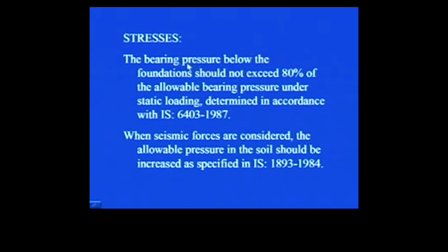Then the bearing pressure below the foundation should not exceed 80% of the allowable bearing pressure under static loading determined in accordance with IS 6403-1987. So this gives us the guideline for how we can determine this allowable bearing pressure under static loading.